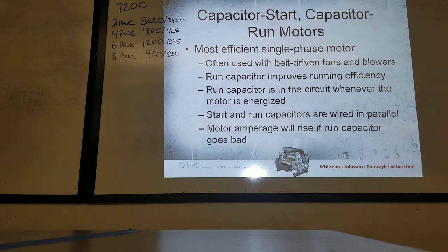Capacitor start, capacitor run motors. Most efficient single-phase motor. Often used with belt-driven fans and blowers. Run capacitor improves running efficiency. Run capacitor is in the circuit whenever the motor is energized. Start and run capacitors are wired in parallel. Motor amperage will rise if the run capacitor goes bad. Okay, so start and run capacitors, they're talking about the other kind of capacitor. Remember the run one?